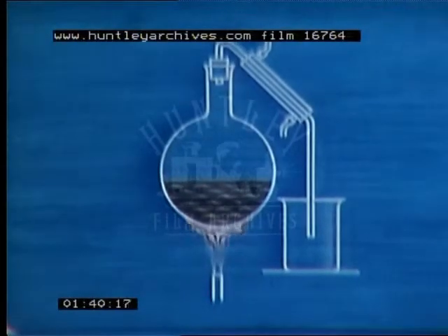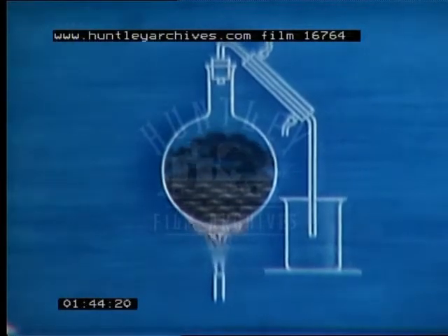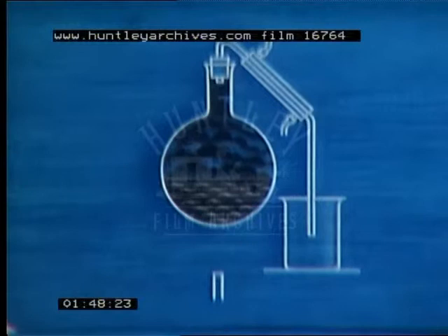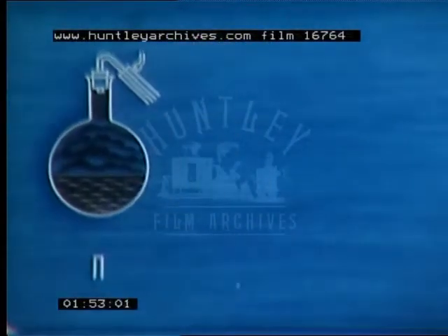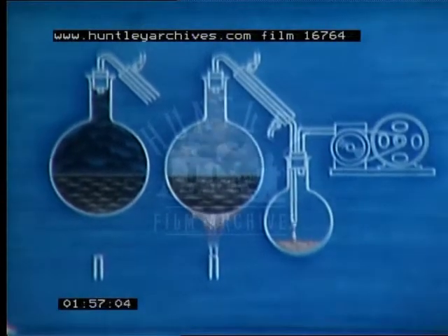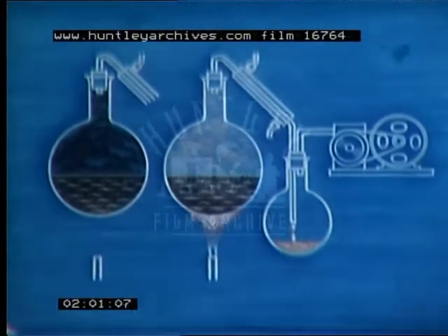This enables us to boil atmospheric residue. Heating at atmospheric pressure results in cracking and not boiling. By reducing the pressure, the boiling point is lowered to below the cracking temperature, making it possible to distill the residue.